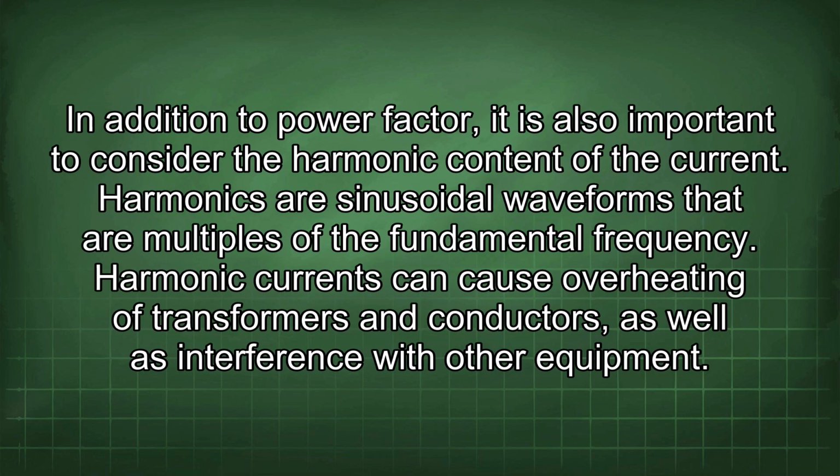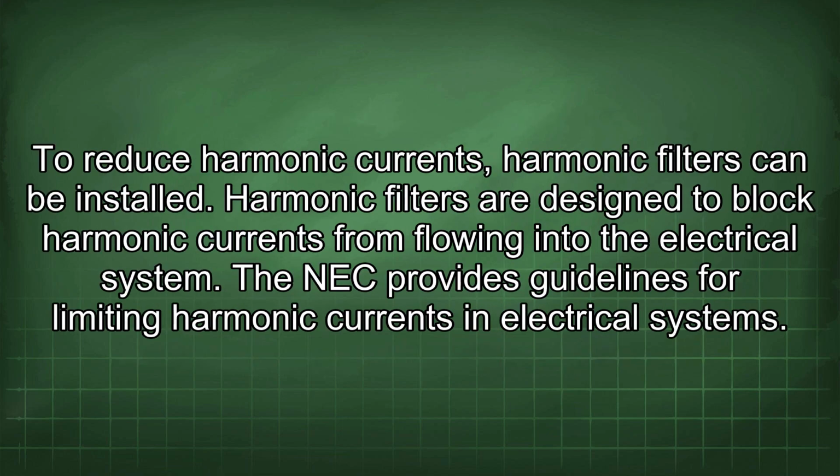In addition to power factor, it is also important to consider the harmonic content of the current. Harmonics are sinusoidal waveforms that are multiples of the fundamental frequency. Harmonic currents can cause overheating of transformers and conductors, as well as interference with other equipment. To reduce harmonic currents, harmonic filters can be installed. Harmonic filters are designed to block harmonic currents from flowing into the electrical system. The NEC provides guidelines for limiting harmonic currents in electrical systems.